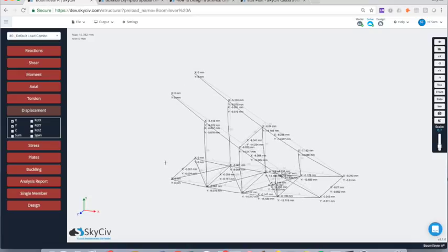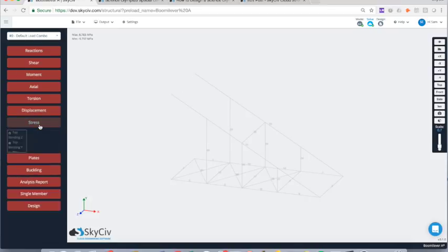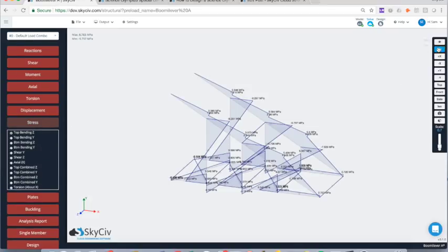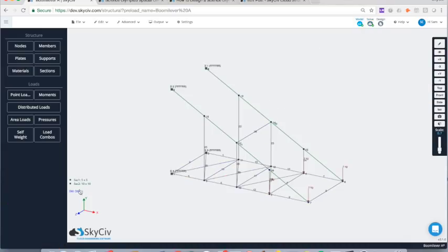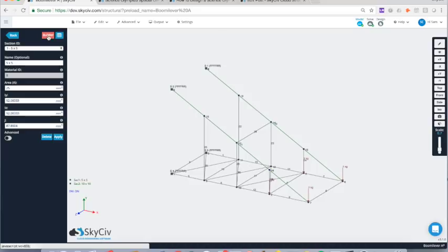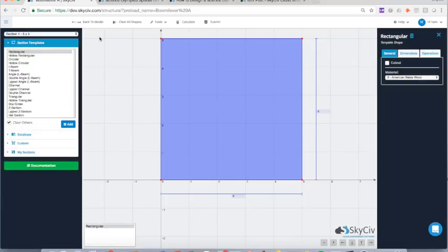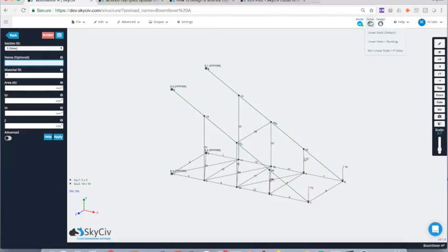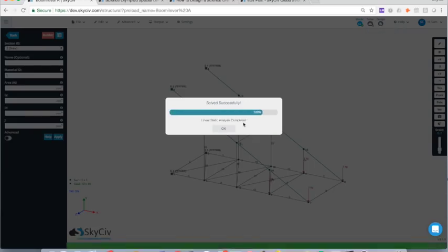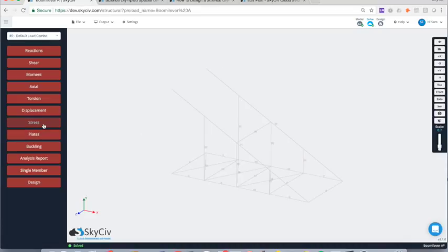That might be okay. Let's check the stresses under that weight. And I'll just confirm that my limit state is okay. 7, now we can still see it's failing. So we might have to increase the strength of the cross section. So let's quickly go back and make some minor adjustments here. And we can change the dimensions from here as well. So let's go to like an 8 mil. And that might be enough to strengthen it up. Checking the stress.